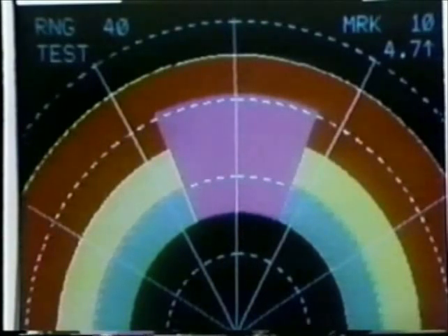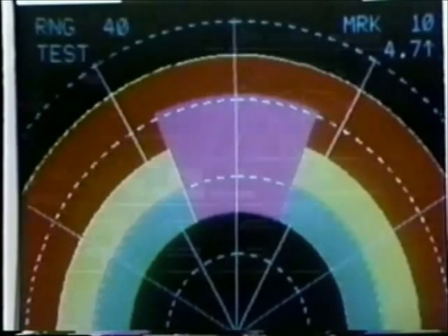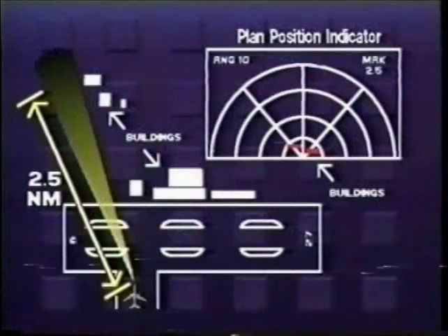While the aircraft is parked at the gate or taxiing in congested areas, keep the radar system in the test mode. Once the aircraft is clear of personnel and fuel trucks, set the mode control to the turb mode if available, otherwise the weather mode, and the range control to 10 nautical miles. Adjust the antenna tilt control to display ground returns as a confidence check.